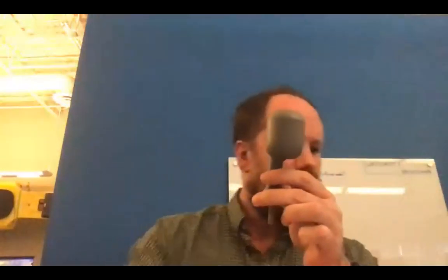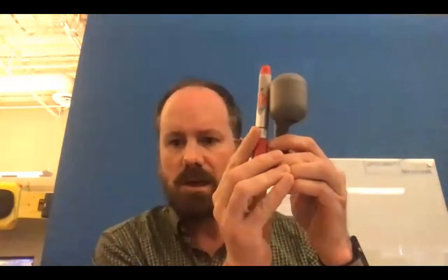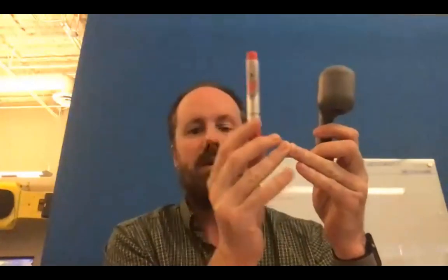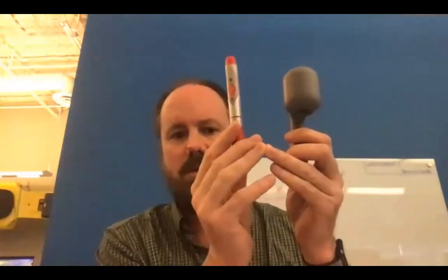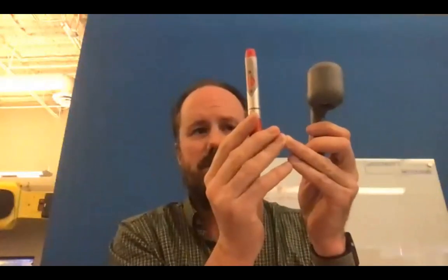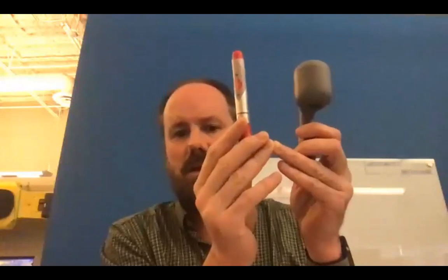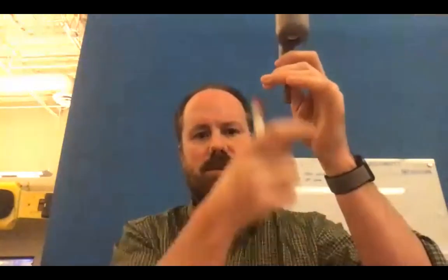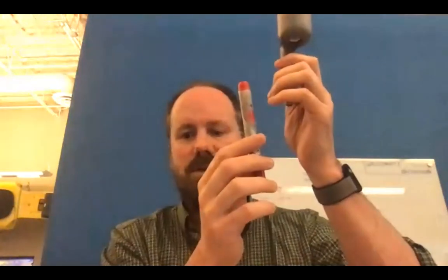Mike Morley, piggyback sensors. In fact, it depends on where you place the sensor, Mike. Here's a conductivity cell. If I place the optode right next to it, then yes, absolutely, you will see a difference that will be measurable. Our rule of thumb, of course, is 15 centimeters, but let's say if you place it approximately 15 centimeters apart, you won't see anything. If you happen to place it lower, for instance, usually the instrument housing is below the CT cell, then we don't see it at all.